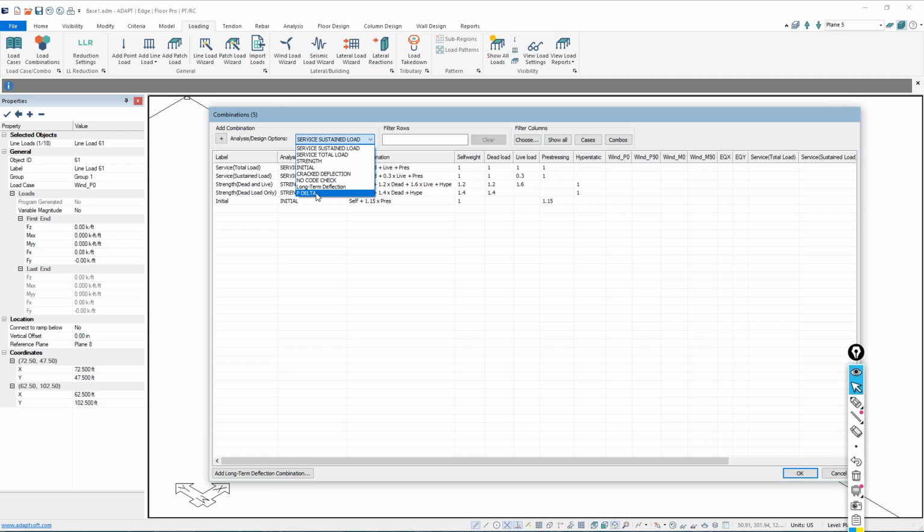When we get into flat slabs, let's say you're designing the slab itself for combined bending and lateral action, we don't design for P delta combinations. That may change based on when this was developed, based on some feedback that we had received, in surveying clients. We felt that we could suppress that for slab design.